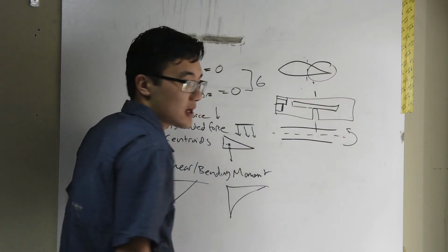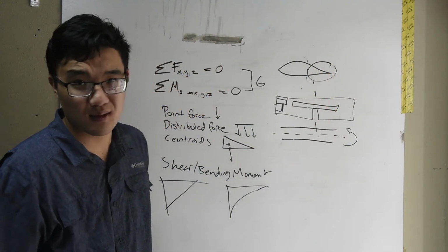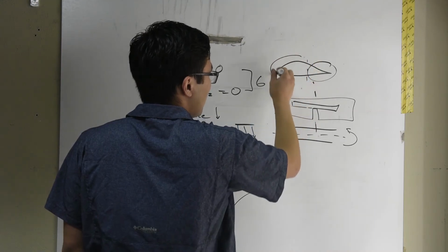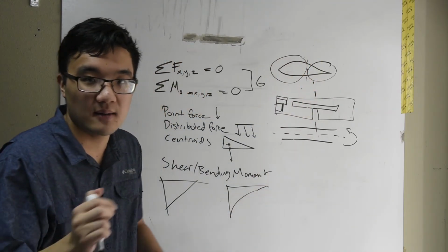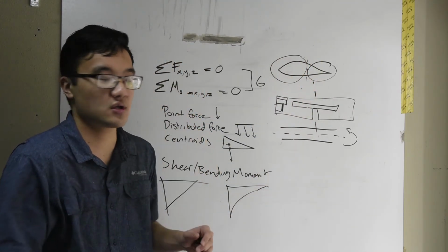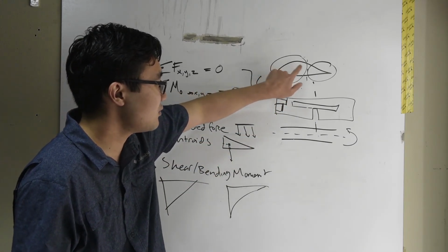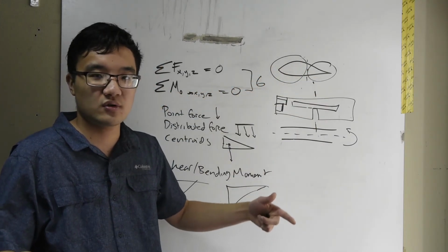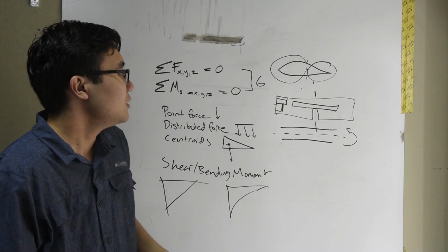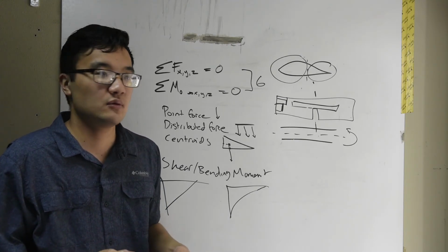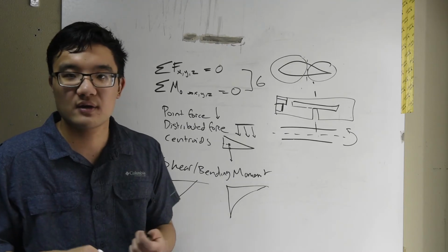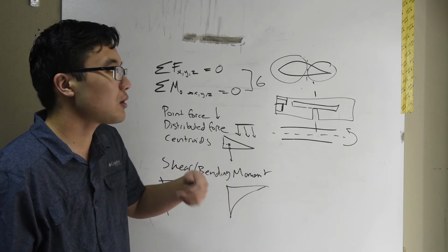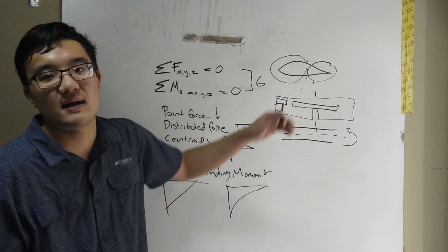All of this stuff is rather thin. It's not contributing to the main strength of the wing. The main strength of the wing comes from this thick leading edge and center portion of the wing. So instead of cutting this away, we cut this part away. Not as important. So again, we take certain liberties, but we do have to work with other constraints. But we do work with the constraints in such a way that it minimizes the effect.